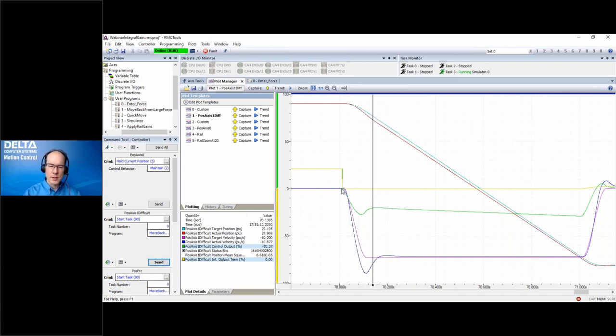But in terms of starting the move, it actually moves very well right there. So let's see, we have a question that came in here. I found on a hydraulic servo valve application that I couldn't get the final position to integrate with just the tuning parameters. I ended up boosting the output bias voltage a bit, and that helped a lot.